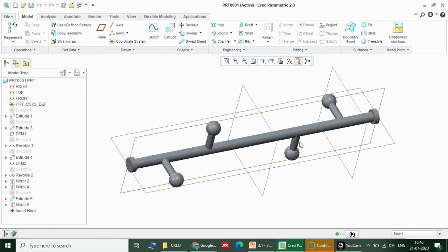Now what I have been talking about is entirely rotating masses only, not reciprocating. First we will see only rotating masses. Rotating masses have two methods of solving: static balancing and dynamic balancing. Static balancing means everything lies in the same plane, even your balancing mass also comes in the same plane. In dynamic balancing, the masses lie across the length of the shaft at multiple angular positions.